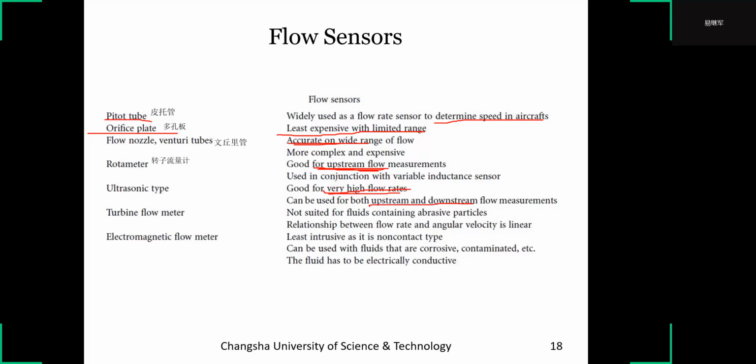Turbine flow meter is not suitable for fluid containing abrasive particles; the relationship between flow rate and angular velocity is linear.